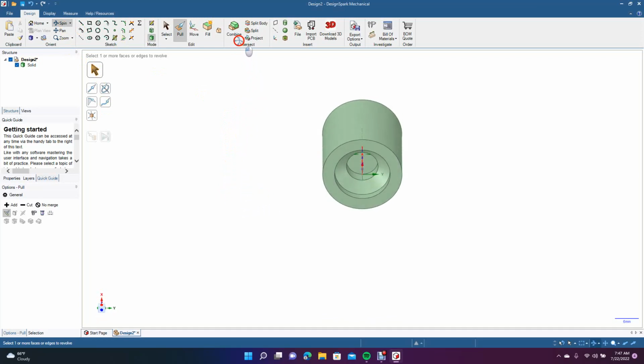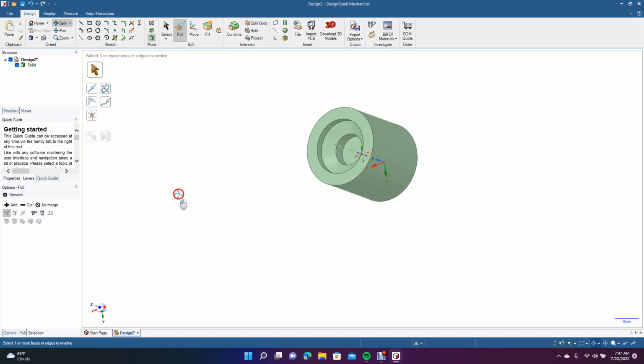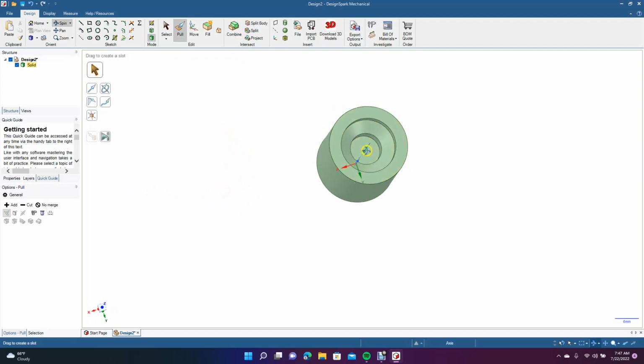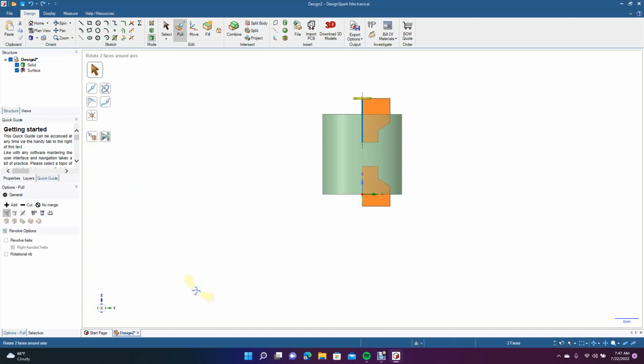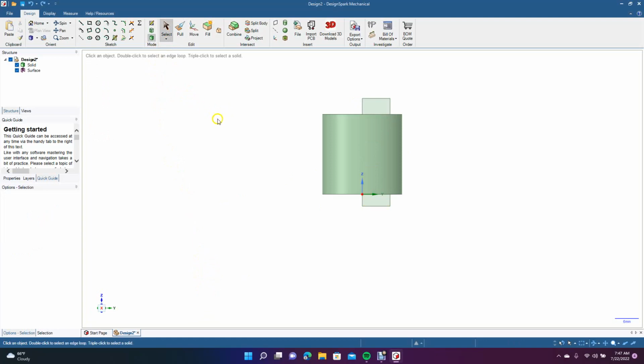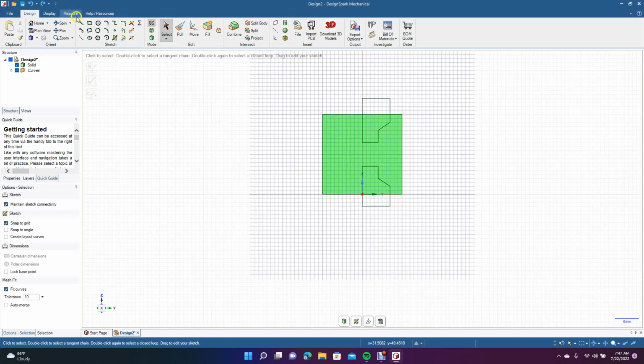The only thing we forgot is to put the part for the truck to go through. Let's do a couple of undos. We'll go ahead and add that. Let's go get our rectangle tool, and then we'll just make an opening.